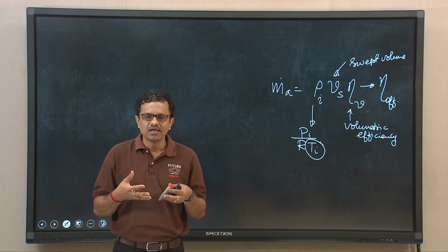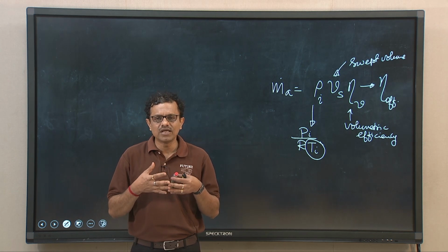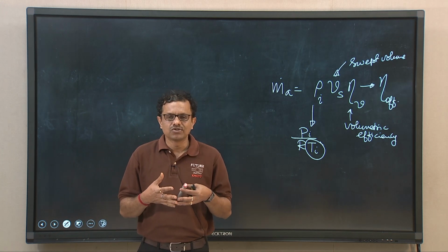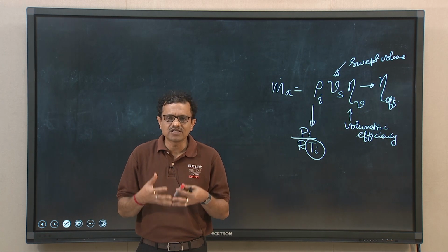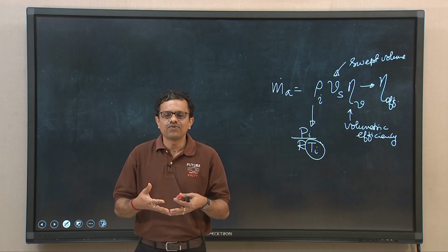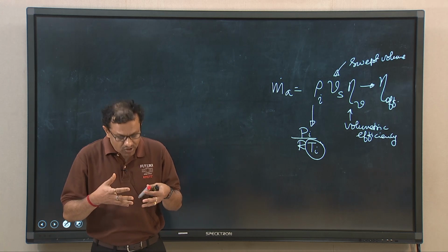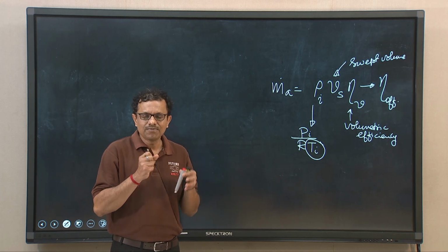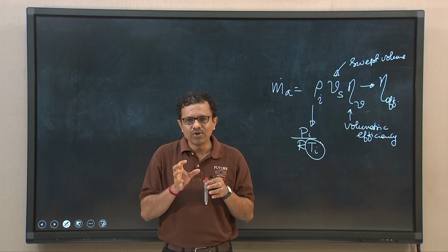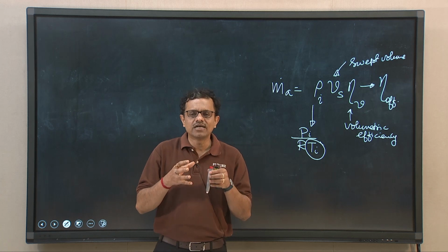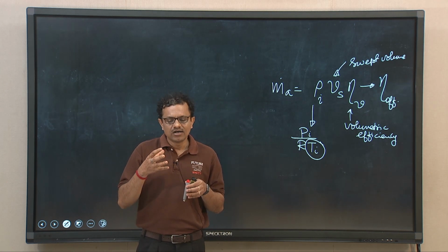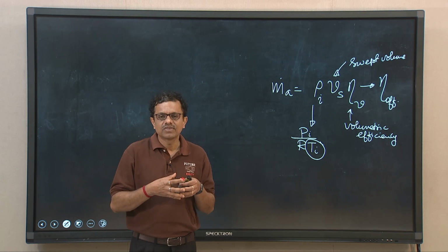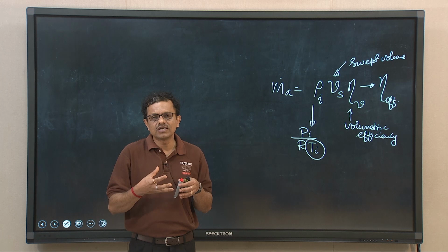So, what does the ECU do if a sensor fails? The electronic control unit should be able to run the engine without inviting additional problems. How does it do that? If a temperature sensor fails, it substitutes a fixed value for that sensor input, sends out a fault code, and continues to monitor the incorrect sensor input.